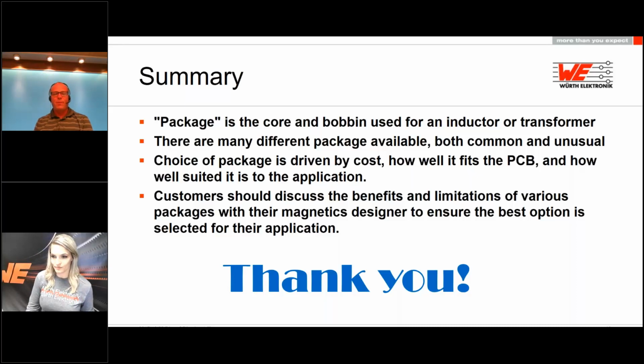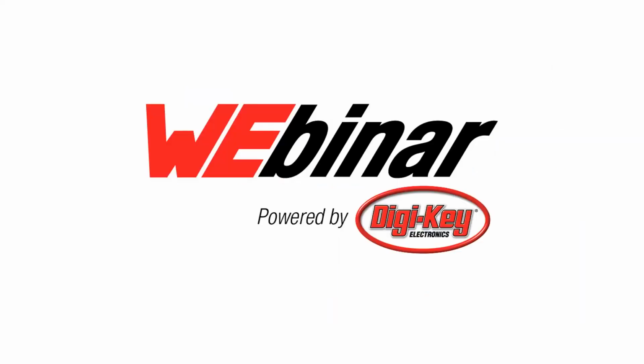It does also have some of the charts I mentioned earlier relating the ability of that package to handle certain power levels. So if you have, say, a 50 watt flyback operating at 100 kilohertz, and you want to know if the EE25 is big enough, or if you need to go to an ER28, you can look that up in there and compare the power abilities of those packages to support those power levels. So, yep, it's definitely a good tool. We use it a lot.